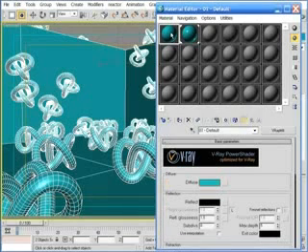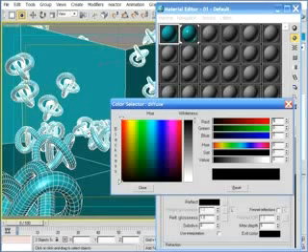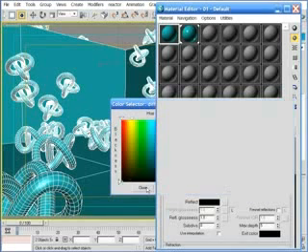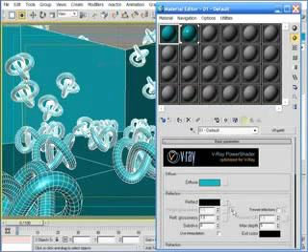Now, to create the same specular highlight with VRay, I need to add a small amount of reflection, just enough so that it's not noticeable throughout the entire material, but rather only on the highlights. I'm going to use a value of 5, and I'm going to make a quick adjustment to the highlight glossiness, which I'll discuss in detail in just a moment. But right now I just want to quickly get a similar appearance to each material, and this will do just fine.